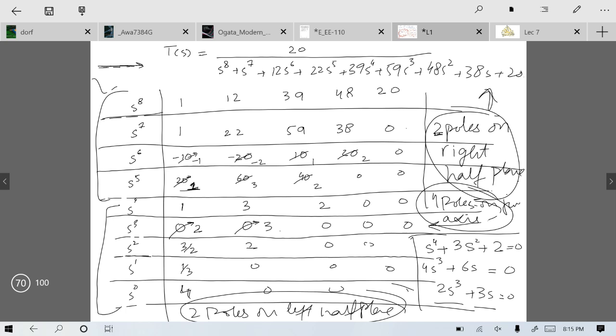So if you had a system in which there are 2 sign changes in total, it has 8 poles, it has no zero row, this is a plain case. If there is a system which is a plain Routh Hurwitz array, a simple Routh Hurwitz array with no zero in the first column or the row, and it is order 8, and if you have 2 sign changes, there are 2 poles on the right hand side and the remaining 6 poles on the left hand side. However, in this case, as you have this 0 row,